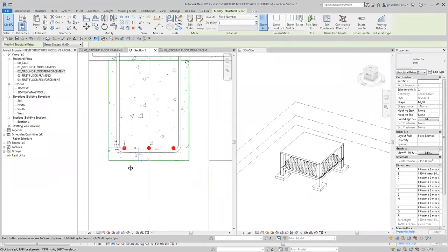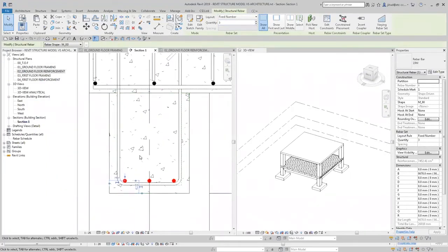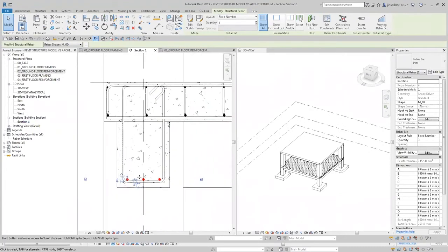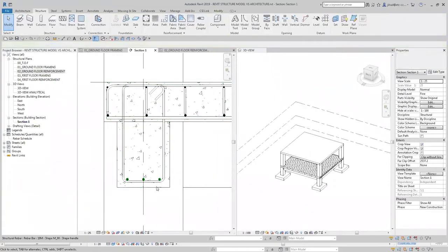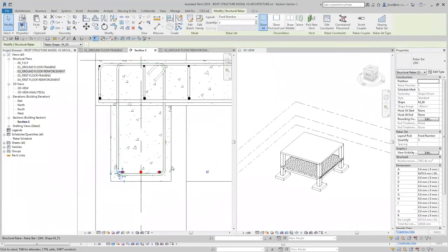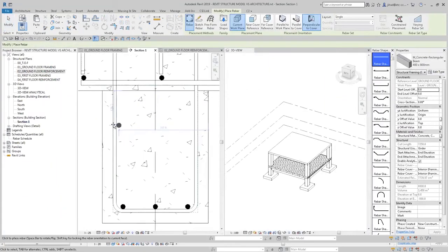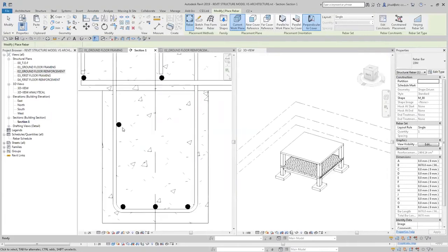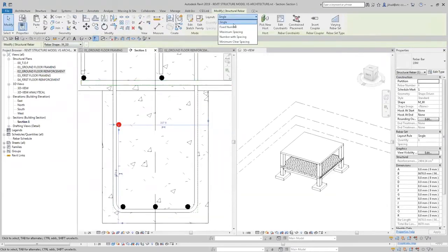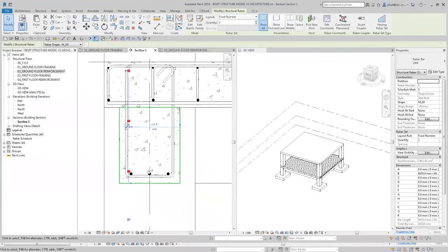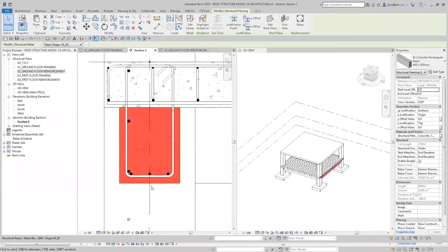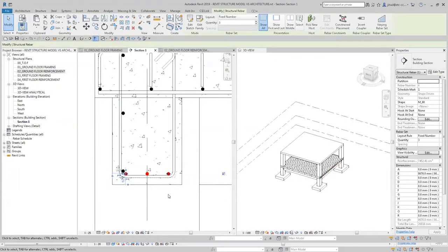We can, therefore, choose where to place the rebar, and this plays a part in the end result, and in what and how Revit spreads the rebar. We can also, to emphasize, make use of all the tools that resemble those found in AutoCAD, in order to help enhance our work. Selecting a specific element in 2D, and having it highlighted in 3D, will help us revisit our work, and double-check its accuracy.